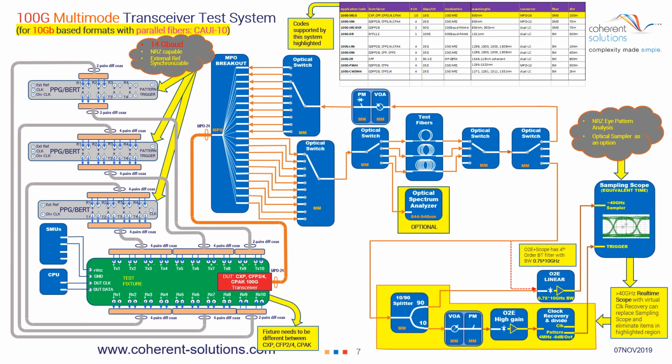The first thing to note on these is there's a nice big box in the upper section here. This contains some of the pertinent information for each of the various transceiver application codes. By application codes, I mean these terms here. The IEEE has terms such as 100G base-SR10, 100G base-SR4, and so on. Each of these application codes stands for a different type of transceiver.